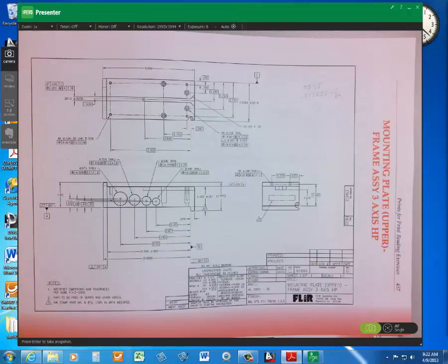So why is there one for the hole and one for the counterbore? So that we have a separate tolerance for the hole, and we're trying to locate the hole to a greater precision. B, we have hole and counterbore, and we're doing our little math. They're both holes, and they're specified at MMC, so we do have bonus tolerance allowed.